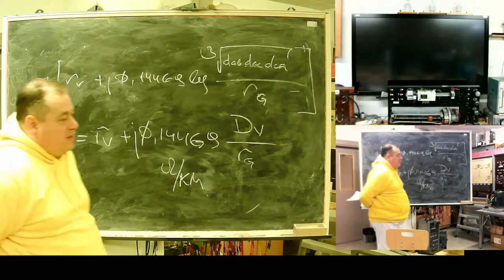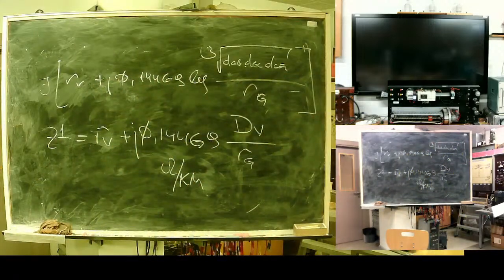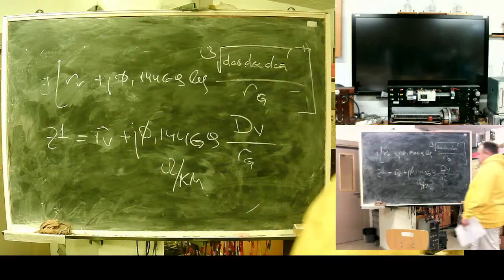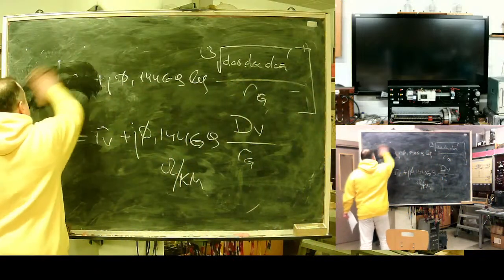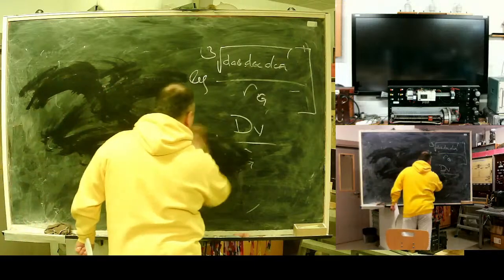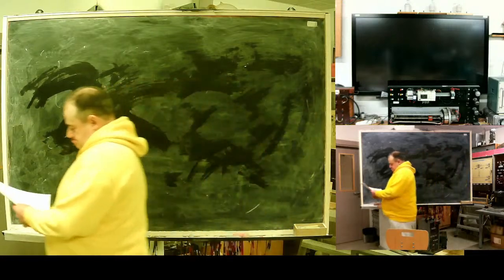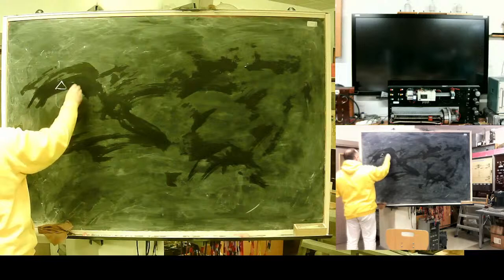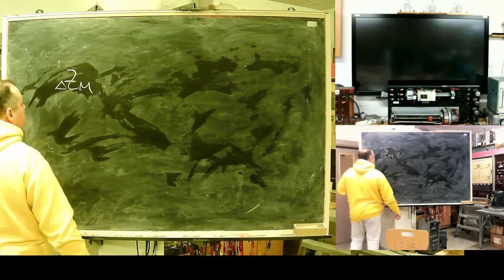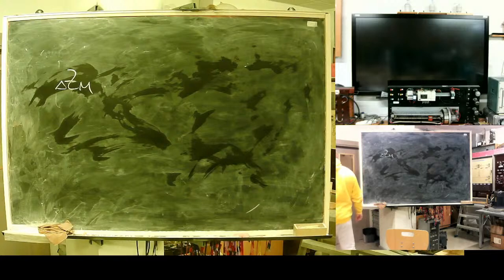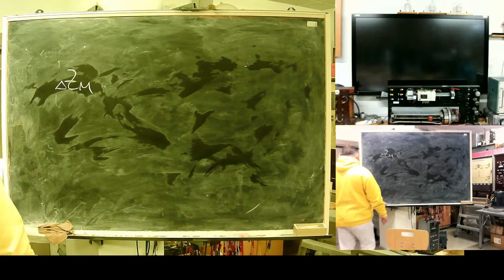And do you see one interesting thing about mutual inductance? The coupling between wires works differently in direct and negative sequence. I can use the value delta Zn to represent the influence of mutual inductance.